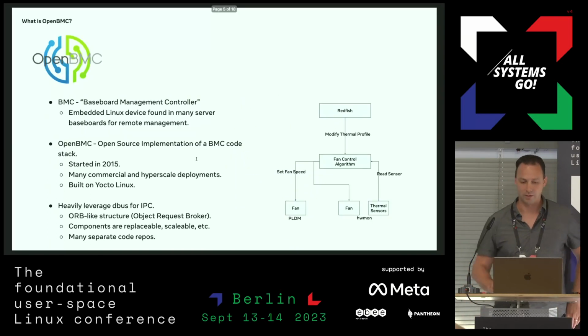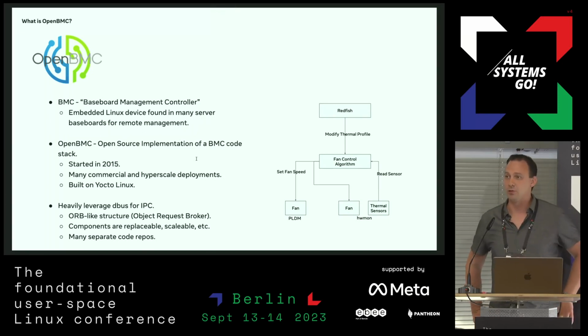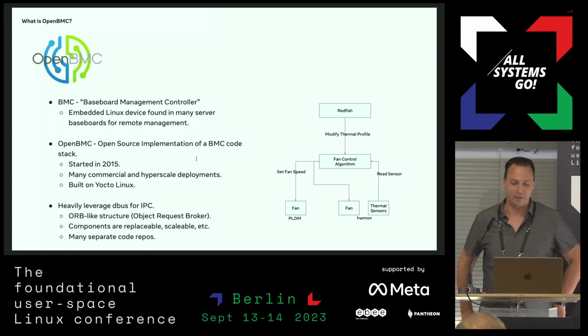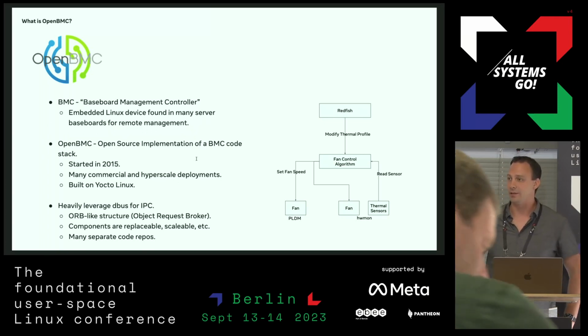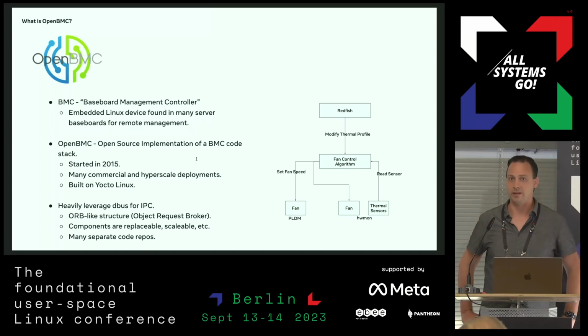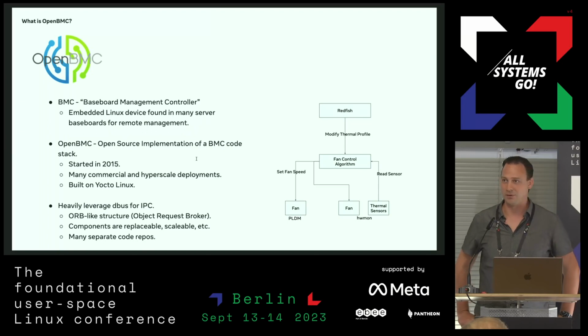So what is OpenBMC? If you're not familiar with what BMC is, it stands for Baseboard Management Controller, which doesn't tell you a whole lot. But most servers in the world have an embedded Linux device that provides remote management. So you think of a server, when you roll it into a data center and it's on a rack, you plug it in, how do you tell it to turn on without somebody pushing the power button? Right? That's one of the things the BMC is responsible for.